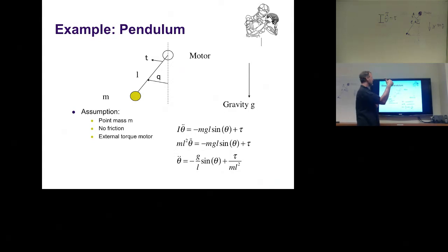You take your thumb, you stick it in the direction of your positive rotation axis, and then you curl your fingers in the direction of a positive torque. So if you look at this, our thumb has to stick into the whiteboard, and we curl in this direction, and that is going to be our positive torque. So we define this here as positive, importantly.